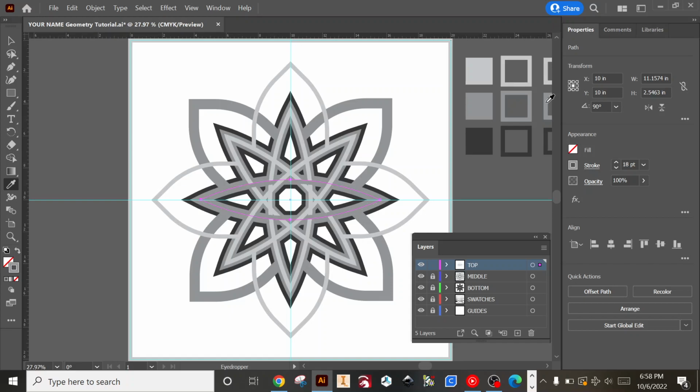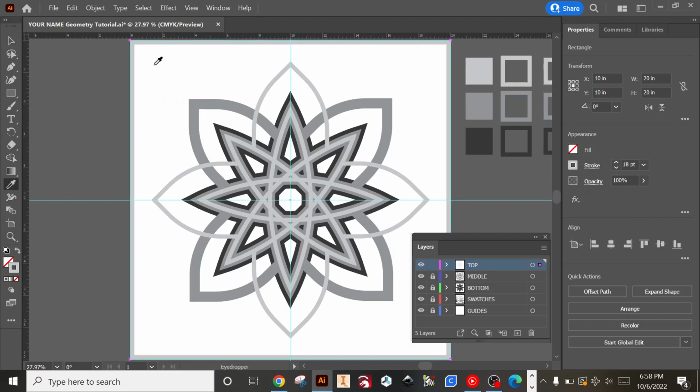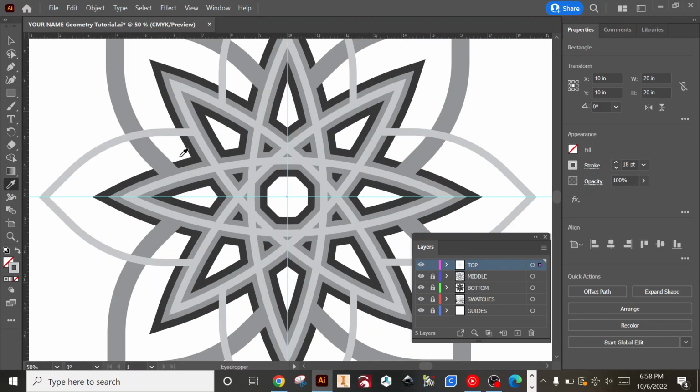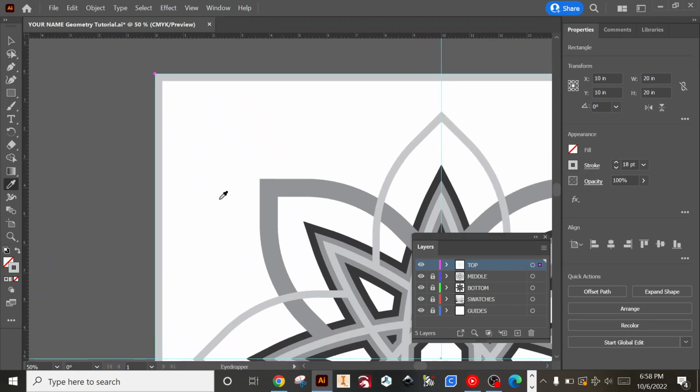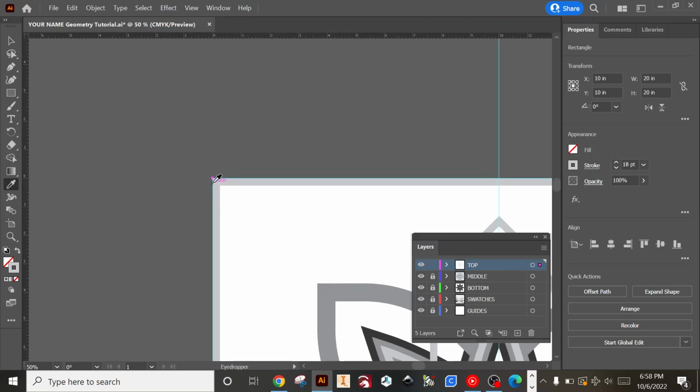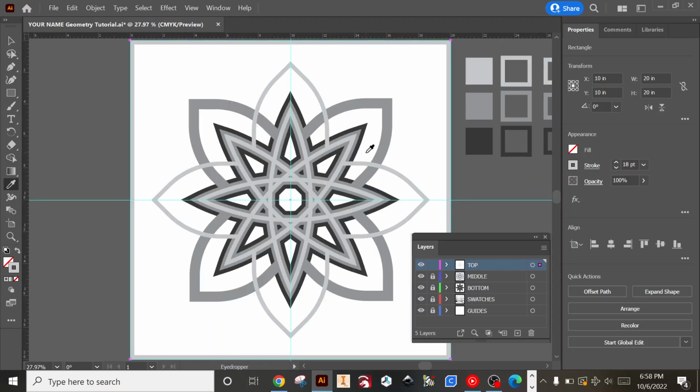I click that, and oops, undo. So I'm going to grab this, grab that. Eyedropper tool, inside stroke. So what it did, now if you look at it, all of that stroke is, and if I hold down the middle mouse button, which is the scroll wheel, you see that now the outline is on the inside of the shape, which is cool. Control 0. So we're going to do that. I want you to select that, and then we're going to go Control Copy.